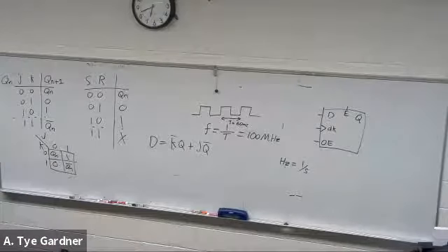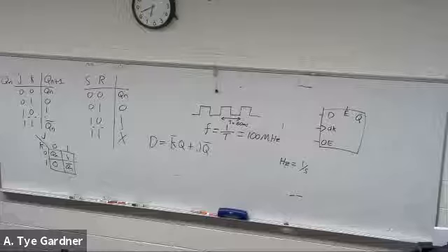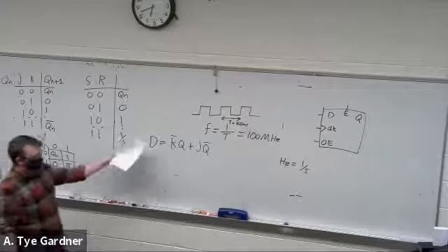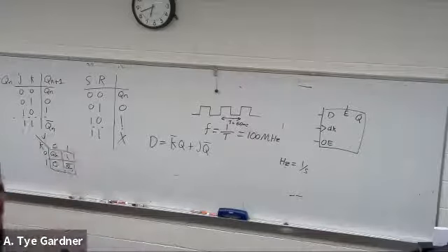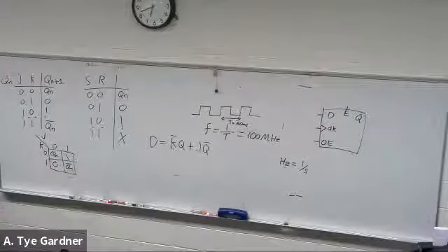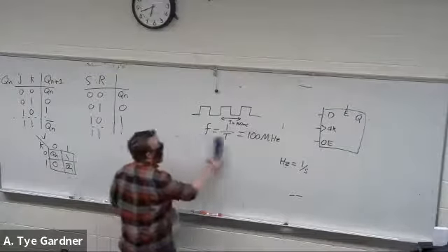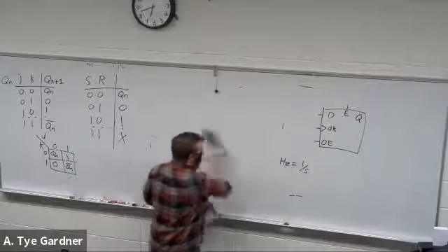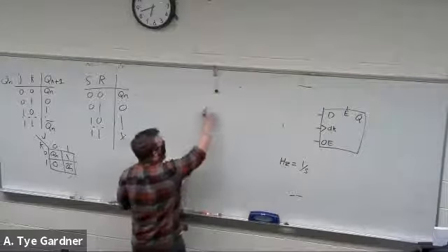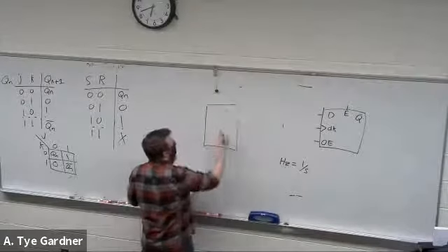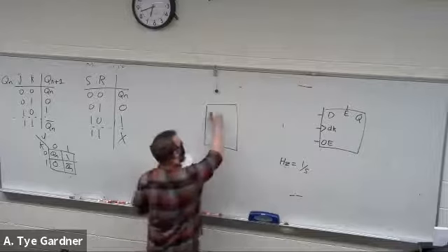Right? I mean, it's pretty simple, and you could almost come up with that on your own for when it's 1, but it's just not that important. What's important is that you understand these truth tables for the JK, because the JK is kind of fun. And the implementation of the JK that we can get away with is really just start with the D flip-flop.